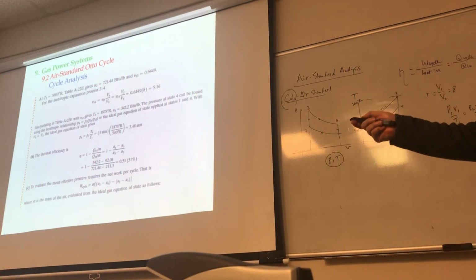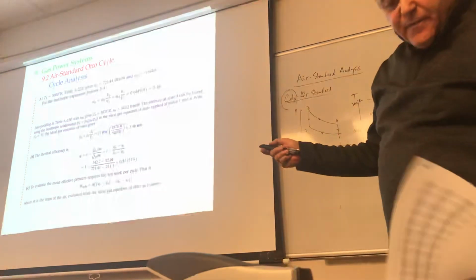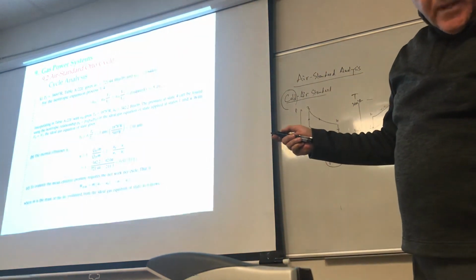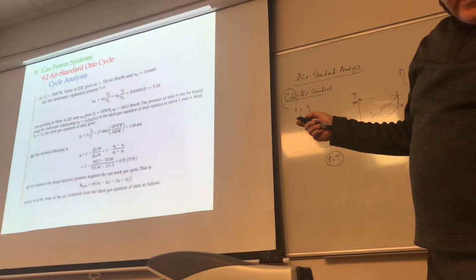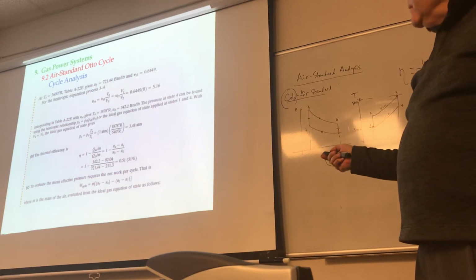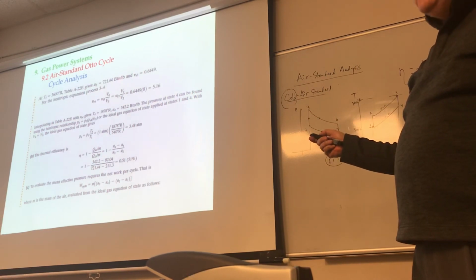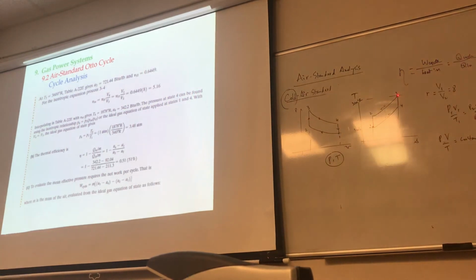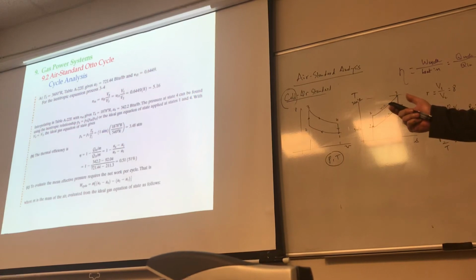I can read directly from the table at 3600, if such a thing exists. I think onto the next page. On page 904 at 3600, I see a value of U of 721.44. Oh, there it is, 721.44. Okay, and because 3 is the beginning of an isentropic process, what should I be reading? The VR value. Okay, what is the value of VR at 3600? It's 0.6449. See, 0.6449.